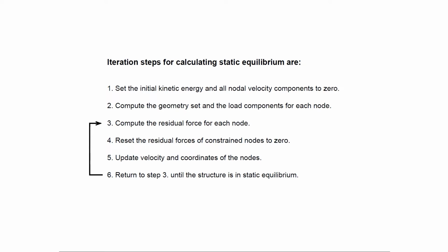So basically, if you have tensile forces between the nodes, they all tend to squish themselves into 0, and that is the equilibrium position. And that's just not interesting for us, because we have no use for such a structure that is clumped into basically a point. But if you constrain the positions of some nodes, so we say some nodes are not allowed to move, then we start getting more interesting, more useful results. So these nodes that are constrained, we basically just say they don't move. Their position doesn't change. So that's step 4.